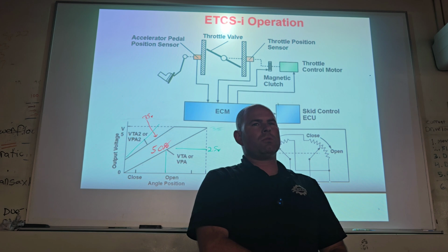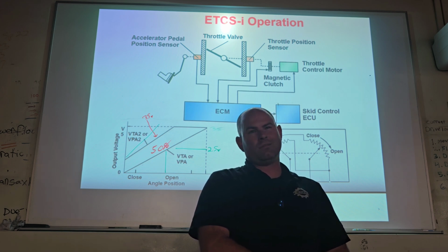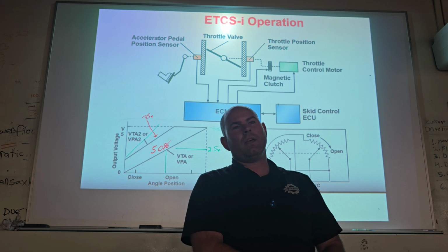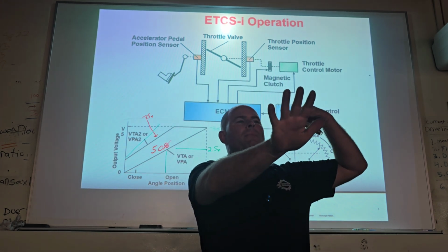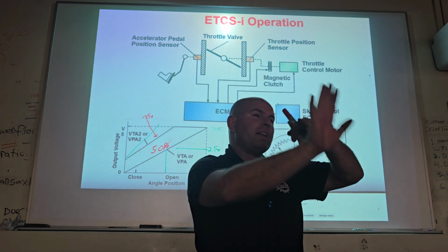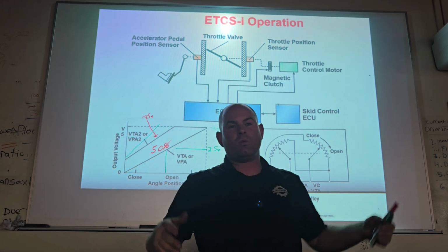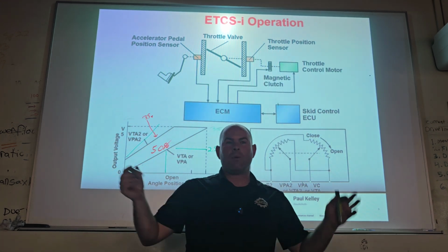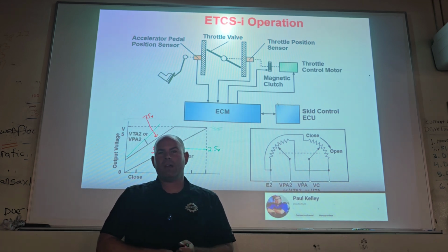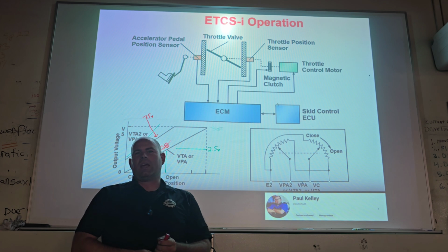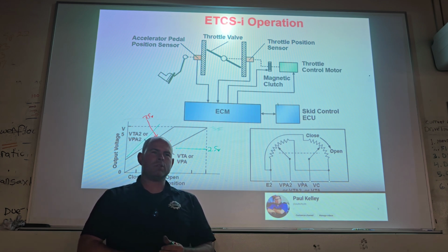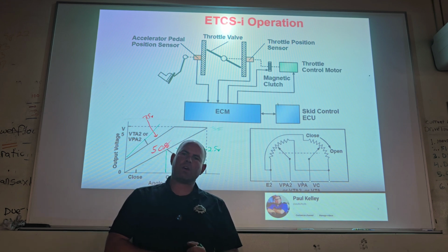Okay? So when the customers were saying, yeah, it's computer controlled and it just accelerated itself, I don't think so. You know what probably happened? Doubled up floor mats pushed the pedal down. With a floor mat, you could actually force the pedal past the first floor mat and it would get stuck coming up. You want to know how I know? Because I had it happen. And I wasn't even at the Toyota dealer at the time. I was at a Pontiac dealer. It was all over the news and people were freaking out. And I specifically remember, you could always fact check me. You're more than welcome to. 80% of the time, I'm telling you 100% of the truth.